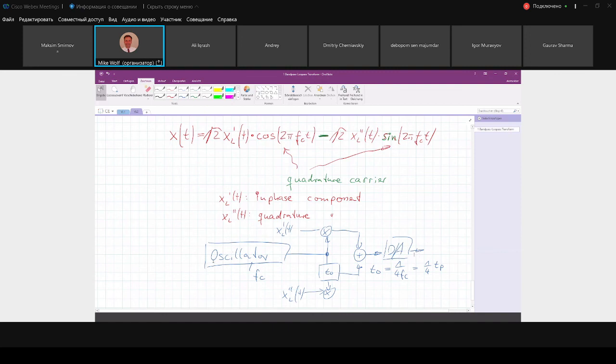This part is digital because the frequencies are so low, and then we do a second multiplication here, which is analog. Now I need to multiply because we have only one real-valued signal, and we shift the whole spectrum, which has an imaginary and a real part, to the final frequency. I call this F delta. It's not FC, it's F delta. So we do this in two steps.